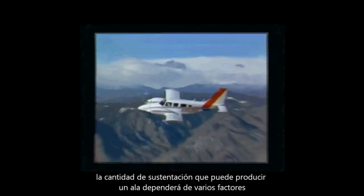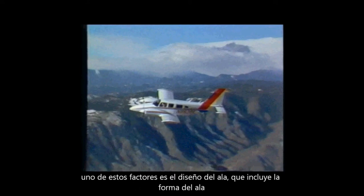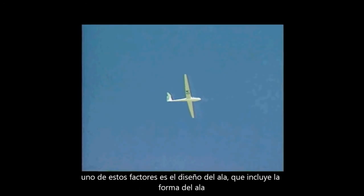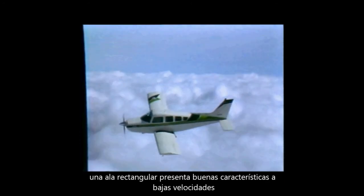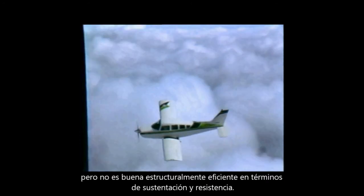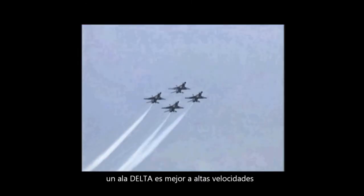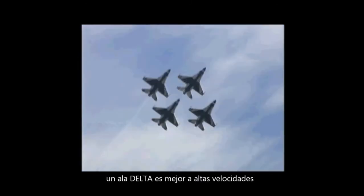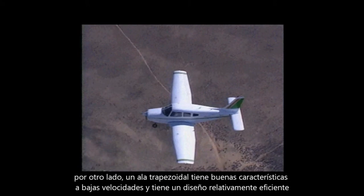One of these factors is wing design, which includes the shape or plan form of the wing. A straight wing has good slow flight characteristics, but is not structurally efficient in terms of lift and drag. A swept back or delta wing is much better at higher speeds. The tapered wing, on the other hand, has good slow flight characteristics and has a relatively efficient design.